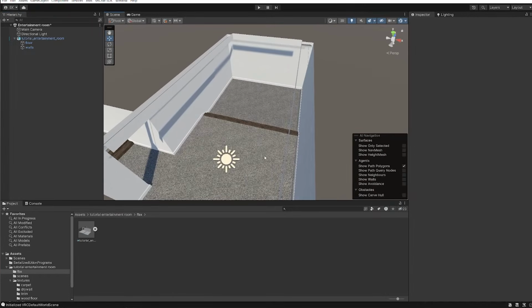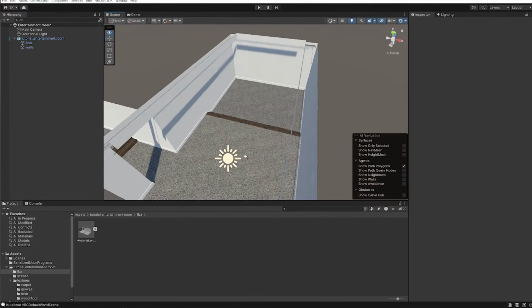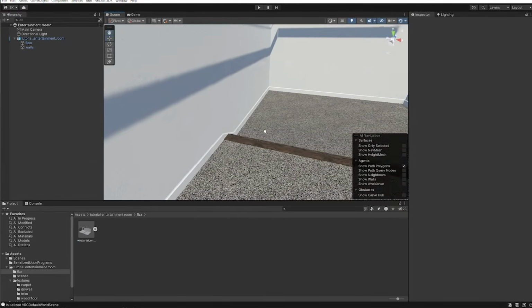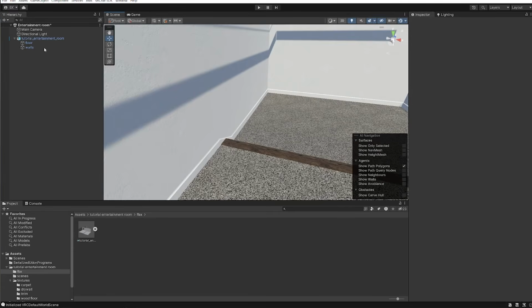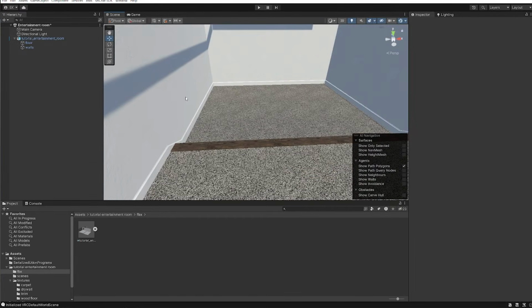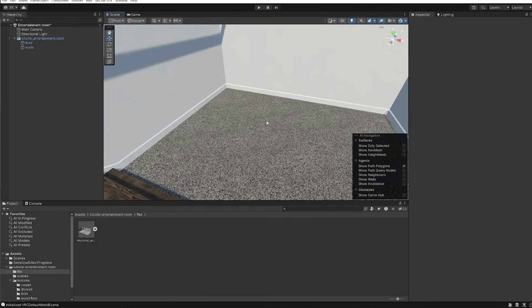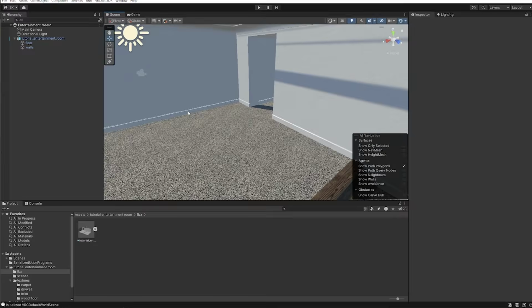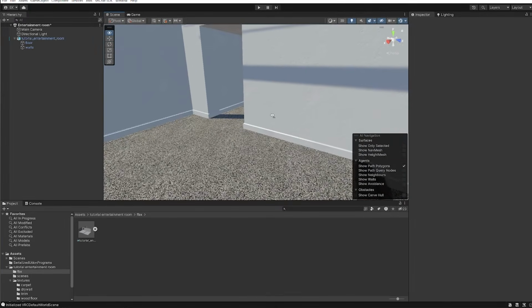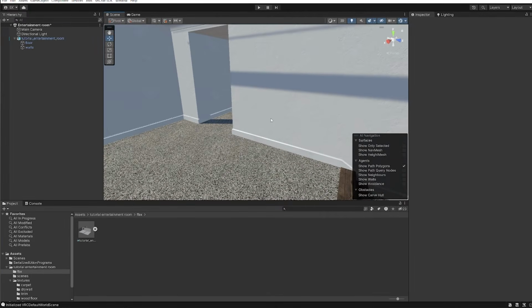And by default, when you bring in an FBX into your scene, it creates one of these prefabs for you. And the reason why that's important is because you can manipulate this and change this prefab in any way that you want. This isn't very important for the base version of this world, though it can be important when you make a chair and you want to duplicate that chair around. If you make changes to the chair, you don't want to make them 10 times because you've got it duplicated out 10 times. So that's why it's important.